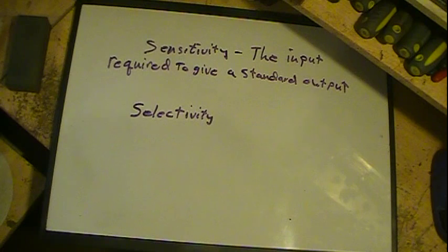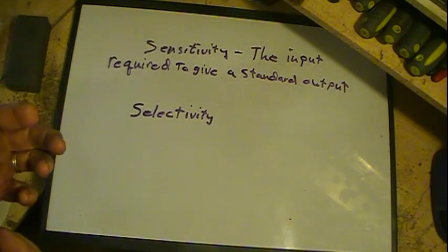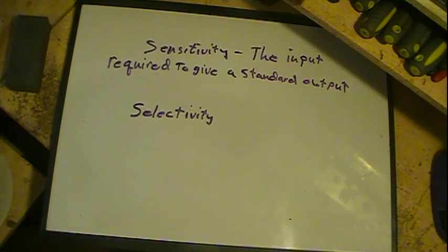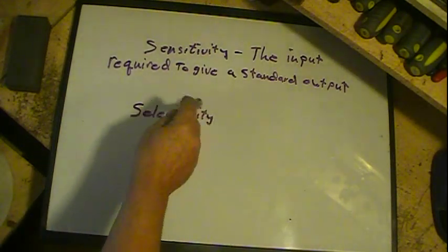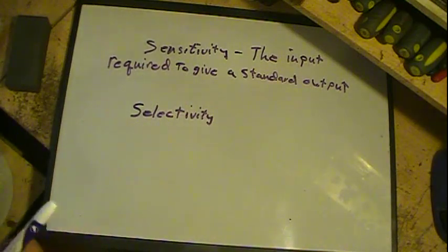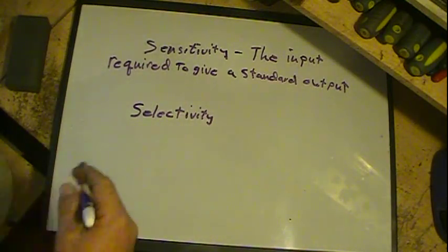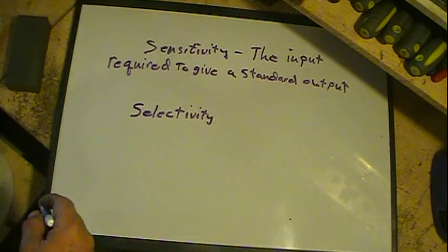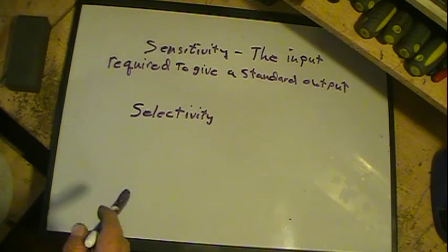Now, signal to noise ratio is another one, and basically it's just what its name says: a measure of how well a radio can pick out a signal in the background noise and amplify it, and leave the noise alone, not amplify it or attenuate it away. And generally signal to noise is used when both of these are measured, when a radio is being tested at the factory, or a design is being tested.